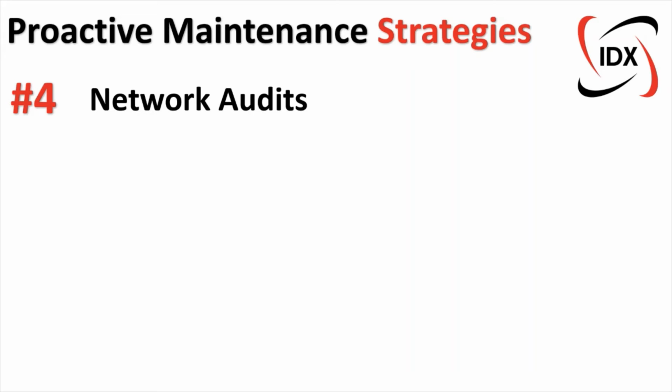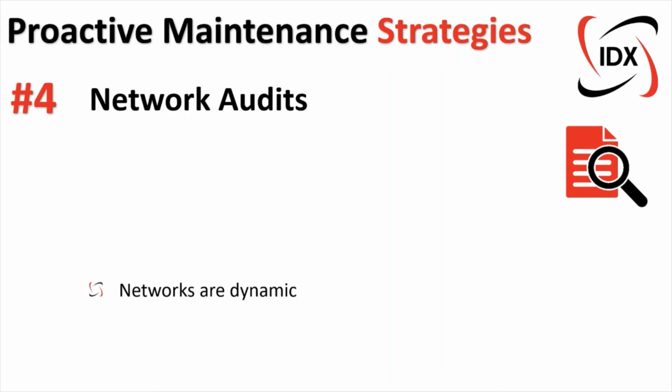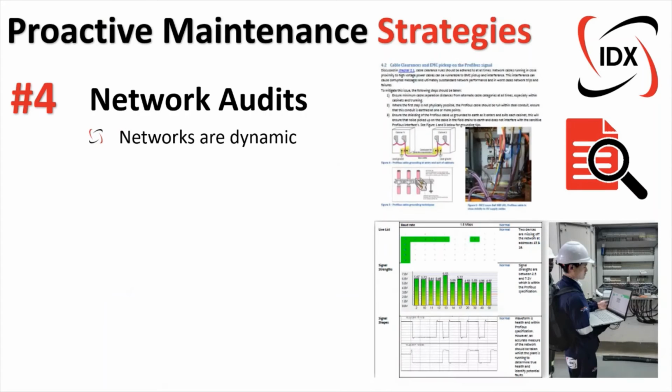Network audit. A network audit should be run not when the network has failed or is failing or causing breakdowns, but ultimately to ensure that the network has the highest possible availability and health that it can have. Now, the important thing to remember is that PROFIBUS networks are dynamic. What I mean by that is very often I would get a request from a site that they would like to certify their networks. They want a certificate that indicates that the network is 100% and will never fail. And unfortunately, I'll never give a certificate like that.